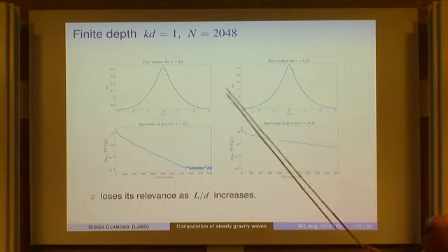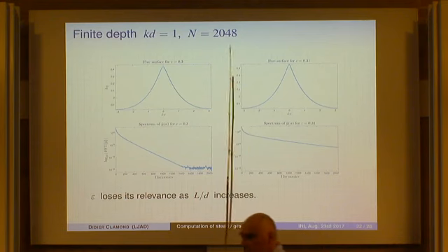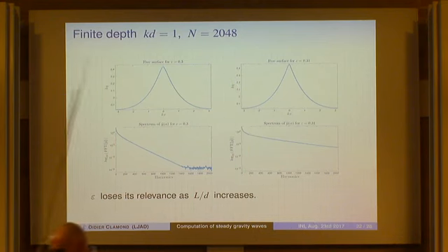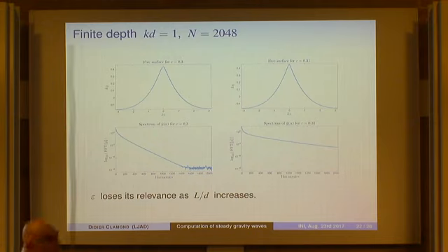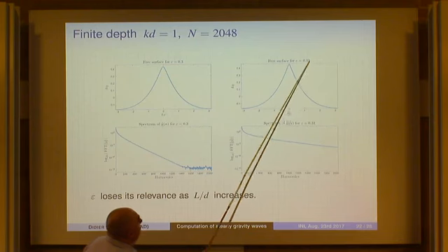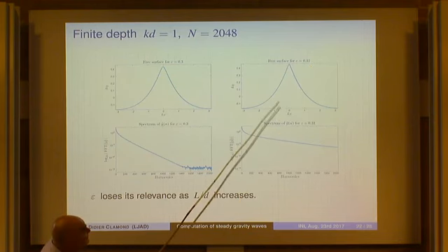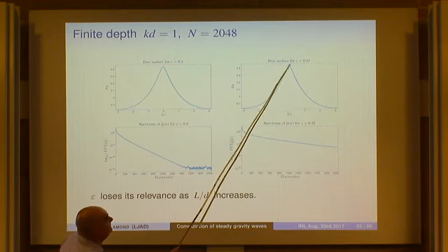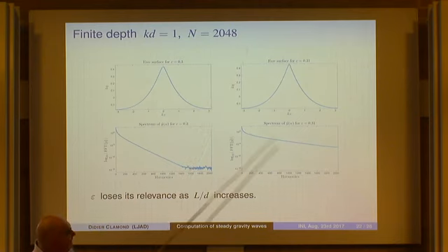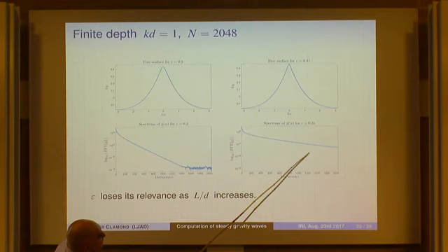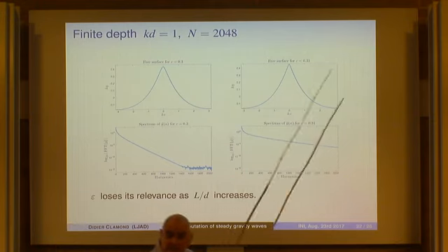It's because epsilon, as I said, is not a good parameter for long waves. The shallower the water, the narrower the range of variation of the parameter epsilon. So actually, epsilon 0.31 and 0.30 are quite different waves, and you see that the steepness here is much greater than here. If you want to compute the solution to machine precision, it's easy. You just have to take 8,000 points. You will get it. 8,000, it's easy.